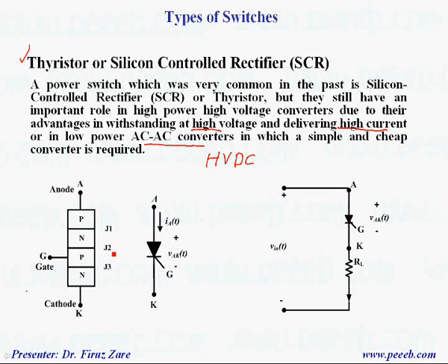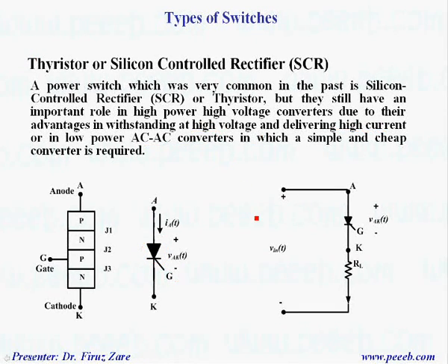So a thyristor basically operates when we apply a gate signal. A thyristor can be turned on, but we cannot turn off the switch by applying a gate signal. So this is a special switch. That means turn on is controlled, but turn off depends on the thyristor current and also the voltage across the thyristor. Suppose that the input voltage is an AC type,